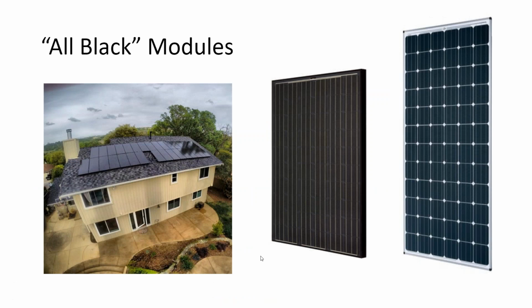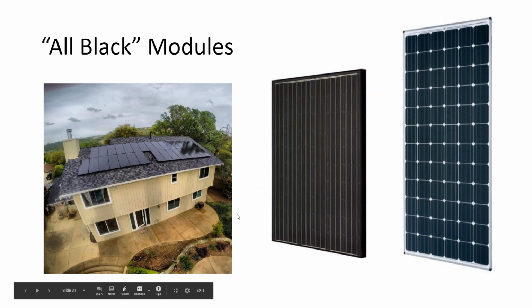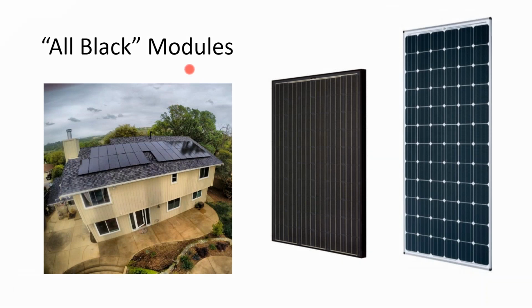When I'm selecting solar panels, particularly for residential, I wouldn't care about this on a commercial site, but when I'm selecting residential panels, what's actually the most important thing to me personally is selecting all black panels. I don't really care who the manufacturer is, and that might be because I work in the industry, so I know there's a dozen really good manufacturers out there, and they're all the same in terms of risk on whether one's going to make it or not. So I'm comfortable selecting any of their products and know that I'm getting a quality product. It's much more important, I think, to buy through reputable vendors like online distributors who might support you if something goes wrong with your order. As a small customer, you're not going to get manufacturer support anyway, and the warranty is really more indicative of product life.